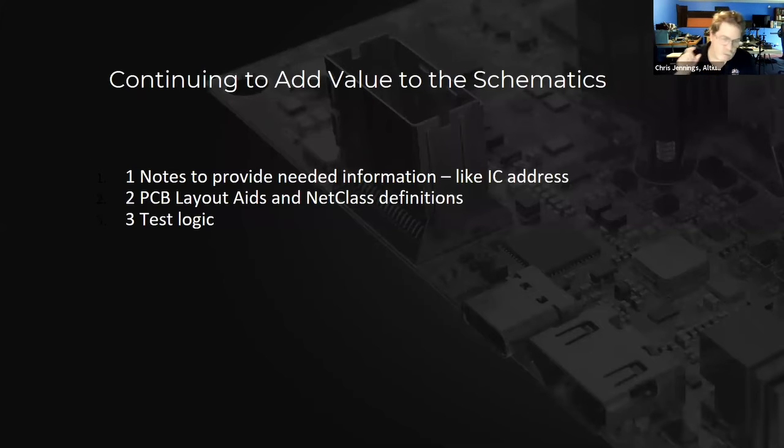If you can go in and put the right answer into an intermediate register and then continue testing the rest of your code, it means you don't have to spend a lot of time recompiling and reloading. So having test logic and considering it and allowing for it up front can be very critical and can really help you in terms of bringing a board up. If you can't get to a signal, then how can you check to see if it's right?